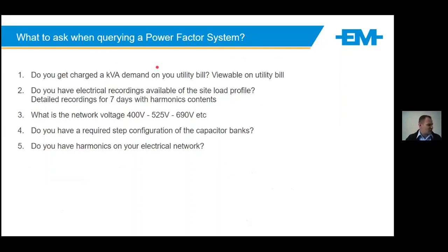So what sort of questions would we have for customers that are querying power factor systems? We'll get a call, and the customer might say, I've got a 63 amp three-phase supply, do I need power factor? Probably not. It's really dependent on the charges you get from your utility. So the first question to ask your customer is, do I get charged on a kVA demand on my utility bill? Ask them for the utility bill. You'll be able to identify if there's a kVA charge.